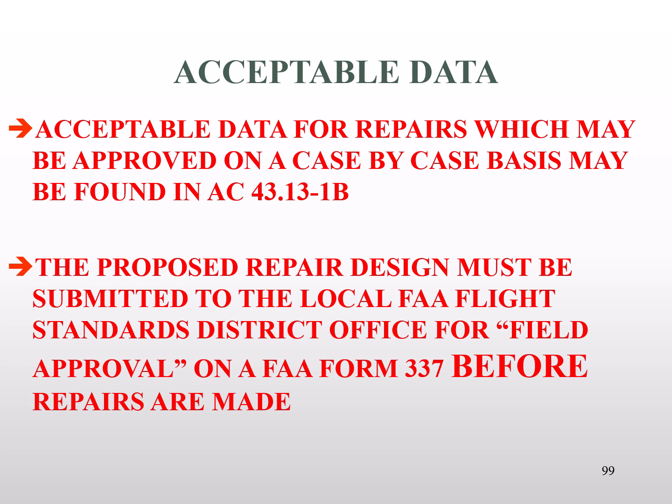So what we could use is the 4313 as a basis to ask permission. We would propose how we would fix it using that. Then we would send it to our local FSDO, or Flight Standards District Office, to get FAA approval. Once they approve it, they'll send it back to us, then we move forward.